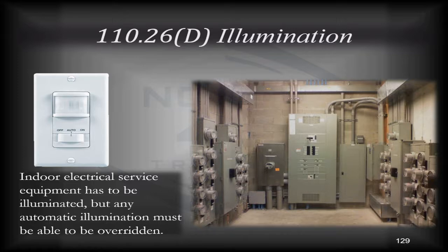110.26d, illumination. Indoor electrical service equipment has to be illuminated. It just has to. If you're going to work on it, you're not going to use a miner's light or something like that, unless there's no power to the room, or you're in an outage or something like that.